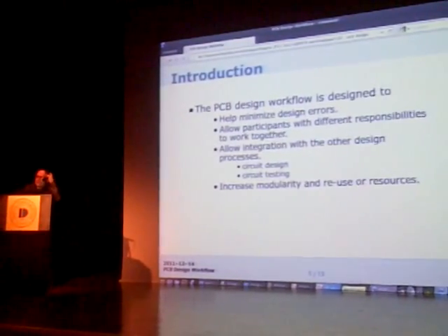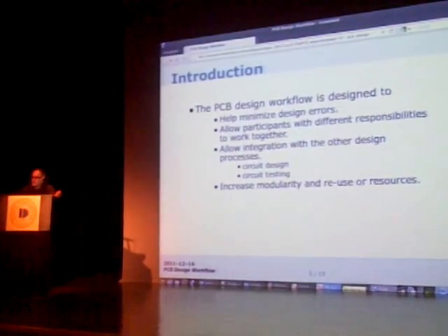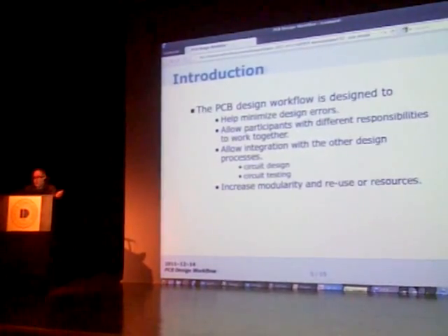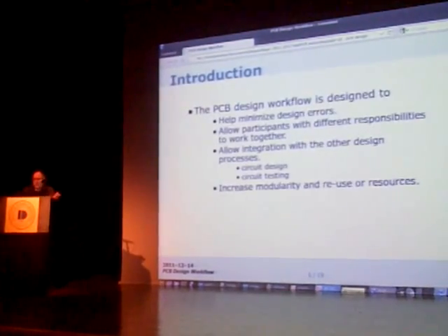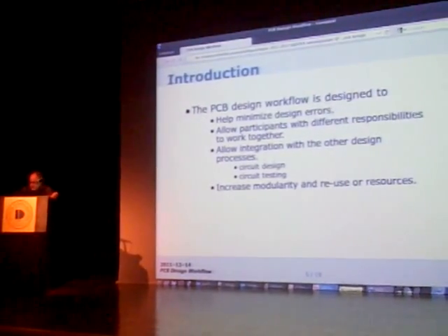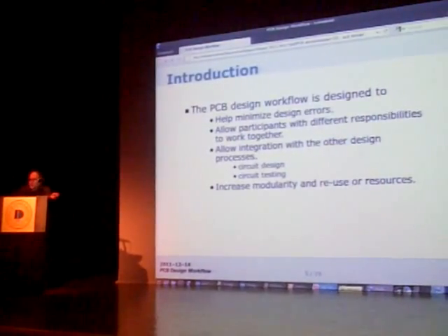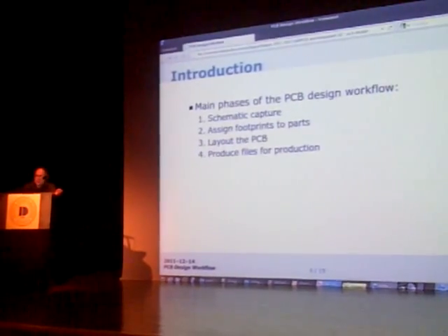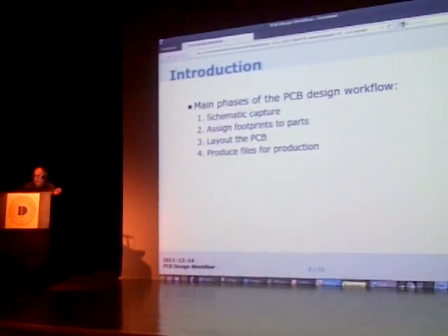The reason for this is that this entire workflow is designed to help minimize design errors. Design errors on PC boards can be very costly because PC boards are costly to manufacture. So that's a big reason for doing this. Another reason is that when you split up the workflow, it allows participants or team members with different responsibilities to work together. One person can be responsible for schematic design, another can be responsible for the layout, and they can actually be working in parallel.